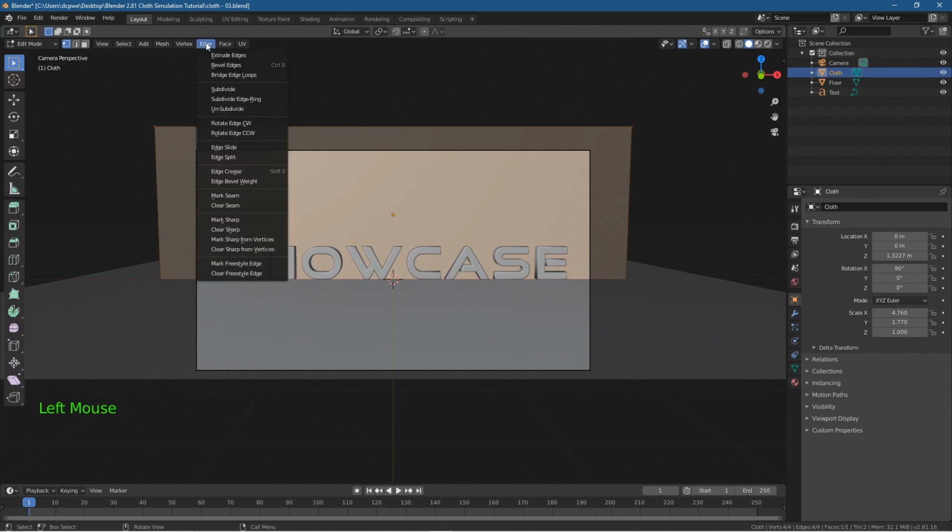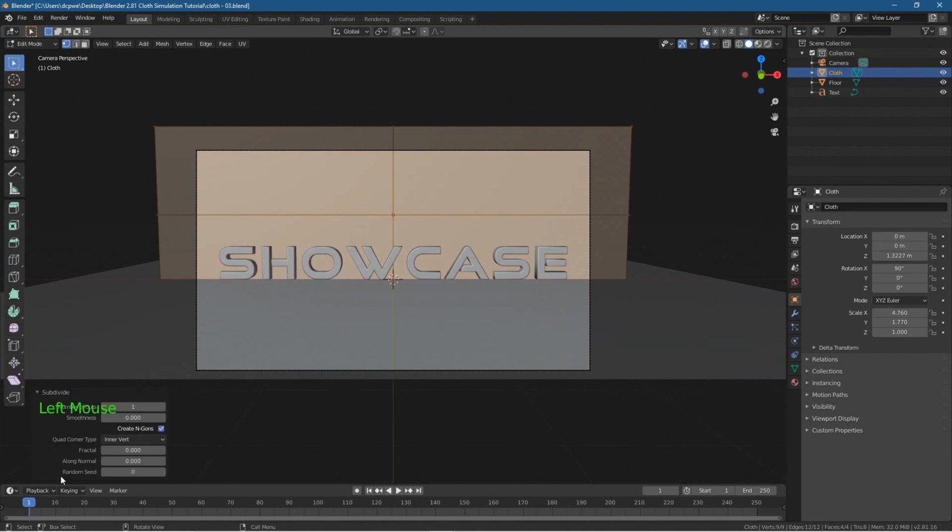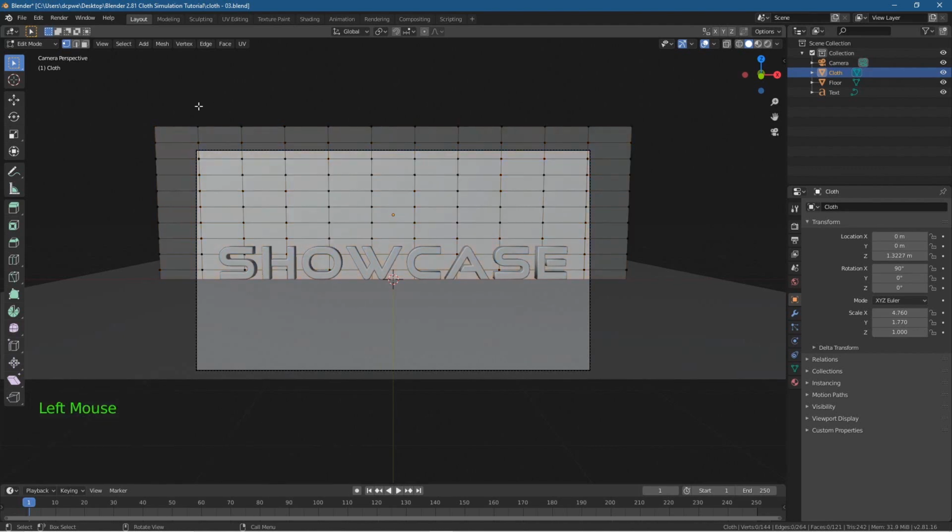And what we want to do is, let's see, we want to subdivide this, right? So let's go to Edge and Subdivide, and we do that once. If we click down here in the bottom, we can subdivide multiple times, and we want to subdivide probably something like 12 times. In fact, we set the number of cuts to 10 here. Alright, and then left click, and that will just give us segments here. We're going to subdivide it again one more time afterwards.